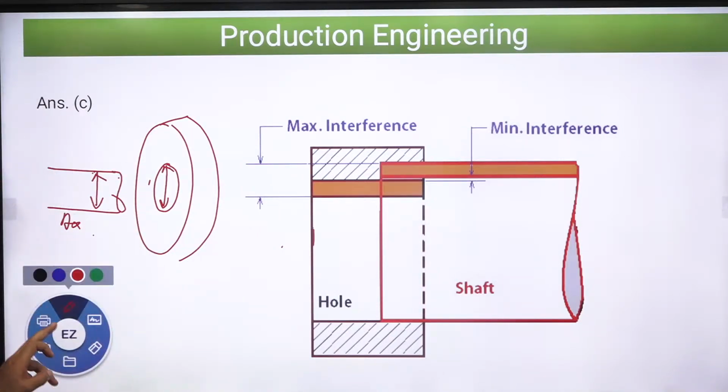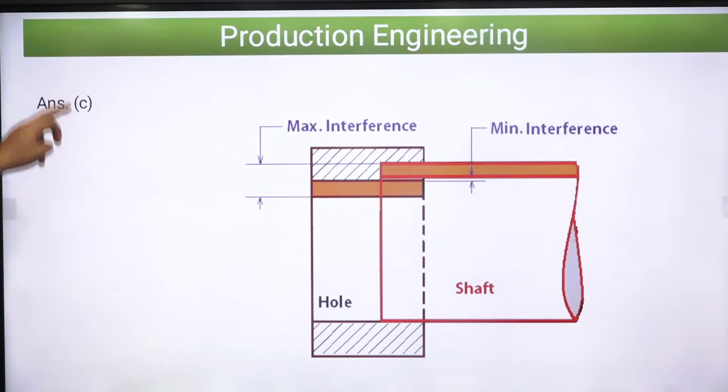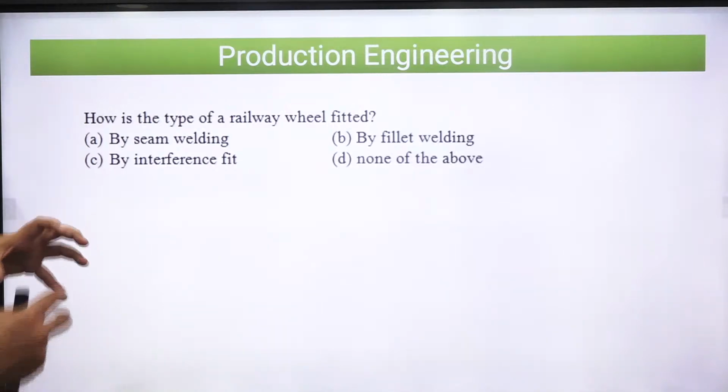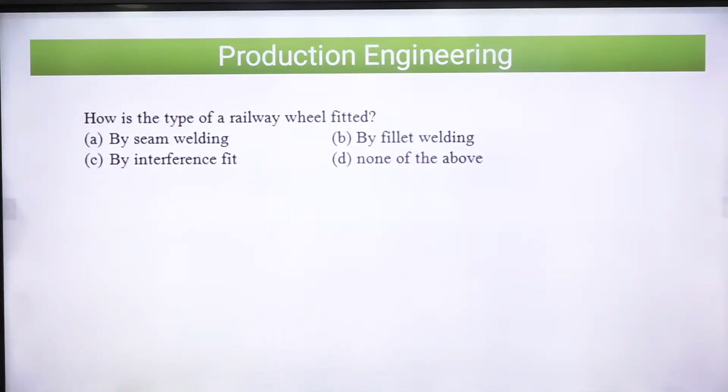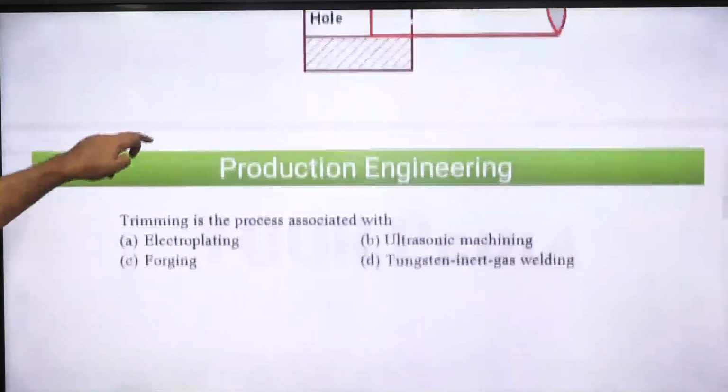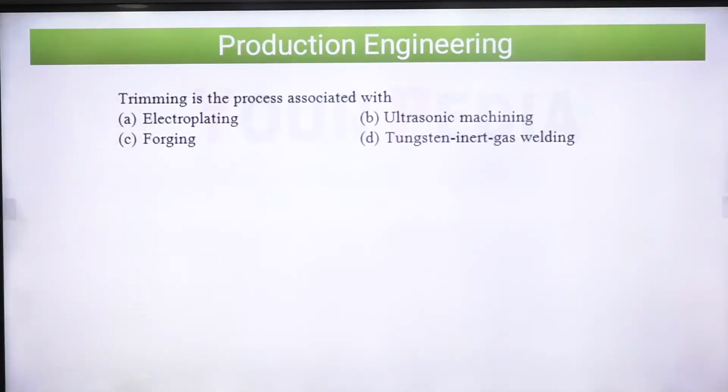The shaft has been made a little bigger and fixed tightly, then we can have an interference fit, and that way it cannot rotate because there is a lot of friction between these two surfaces, and plastically they have been joined together. Look at this, just go through it.